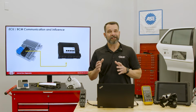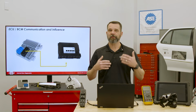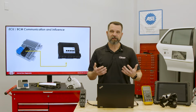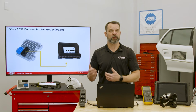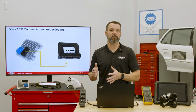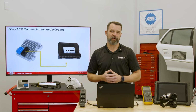And so essentially, the ECU is continuously sending data like speed, ignition mode, engine status, and security status to the BCM, and then the BCM uses that information to control things like the door locks, window motors, and the switches. And without that data from the ECU, many of those body functions would either fail completely or at the very least behave a little strangely.